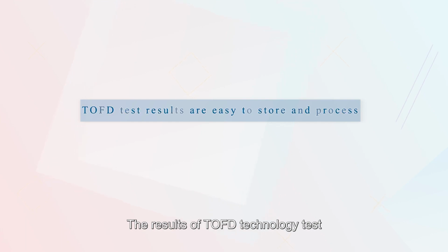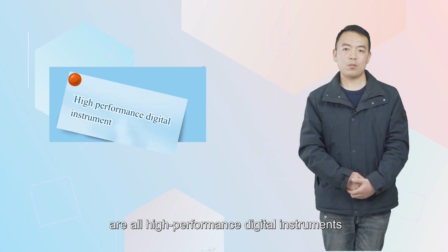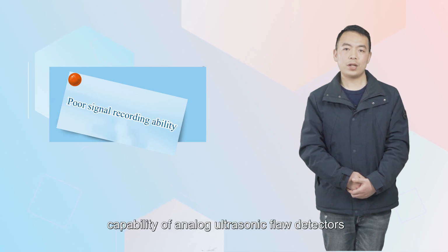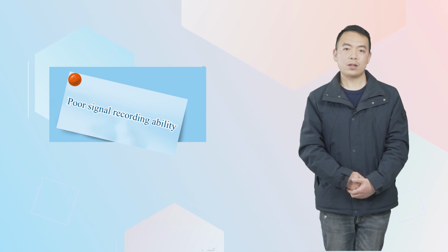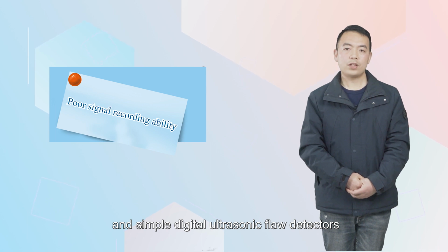5. The results of TOFD technology tests are easy to save and process. The TOFD testing systems currently in use are all high-performance digital instruments, which completely overcome the poor signal recording capability and simple signal processing of analog ultrasonic flaw detectors and simple digital ultrasonic flaw detectors. 6.